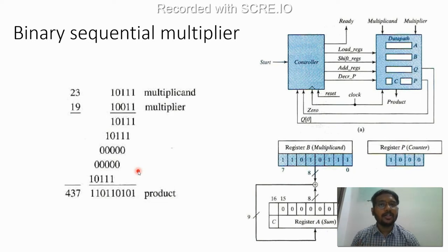In this design, we will be using only one register as an accumulator for the accumulated partial product, let's call it register A, where the partial products get updated, shifted and added according to the control input. This is decided by the controller.